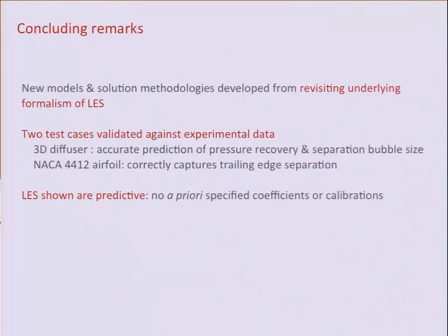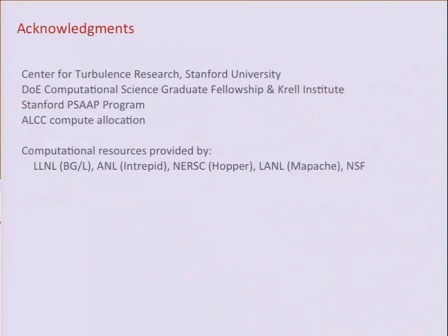So just to conclude, I showed some results from new models and solution methodologies. And these are really developed from revisiting the underlying formalism of LES. I've just presented those 2 test cases validated against experimental data. And I'd like to emphasize that the LES results shown here do constitute predictions. There are no a priori specified coefficients or calibrations in these models. There's usually a multi-resolution piece to help determine what those coefficients should be during runtime, and those are adapted each time step.